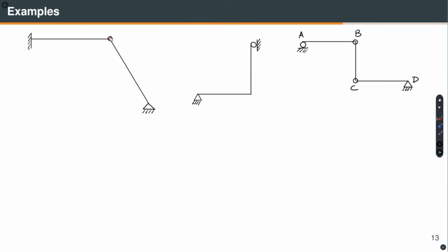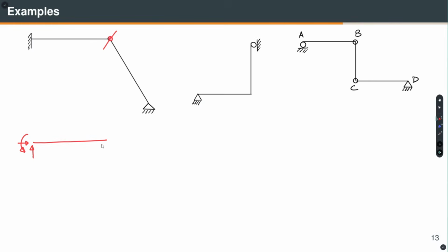Well, this is an internal hinge. So, what I will do? I will cut it here. So, if I cut it here and draw the free body diagram, for the beam, this is the free body diagram. These are the 2 reactions, one horizontal, one vertical, and a moment. So, when I cut at the internal hinge, it is like this, right. So, it is allowing rotation. So, there is no moment transfer, right. So, there are only 2 reactions like so.